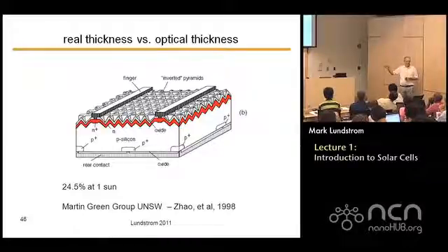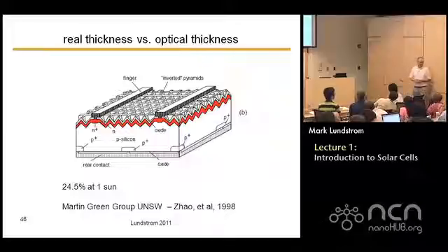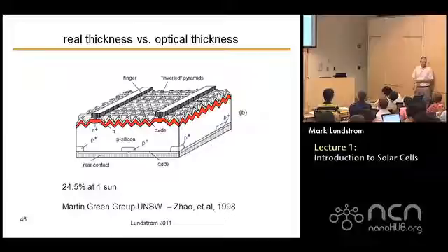These P-N junctions are very small, so the carriers can diffuse to them and get collected. But there's a lot of recombination and things that happen in the P-N junction, so if you can minimize that, those are called point contact cells. Now, the area of the cell can still be very big, but the area of the P-N junction itself can actually be quite small.